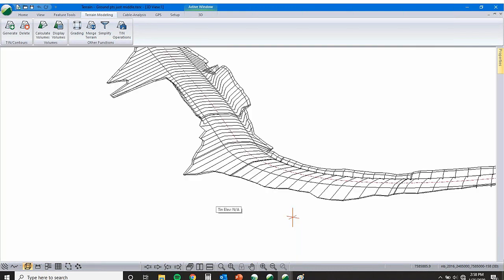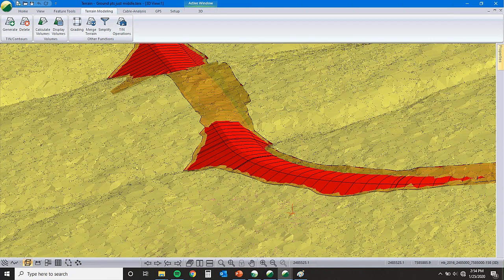For the road side of things, as previously mentioned, we're going to consider the road as a 3D object rather than just a line. So we have our center line, and attached to that we have our cross-section geometry, and how the two interact is how we come up with a good design. So here we can see we've got a decent fill. We could figure out, okay, we want a certain length of culvert in there, capturing some drainage. We see we've got a decent amount of cut going on here, and we've got some fill on either side. So we can use that to come up with a pretty good plan, so we're balancing that this cut amount gets flopped back into here, and make a quick road.